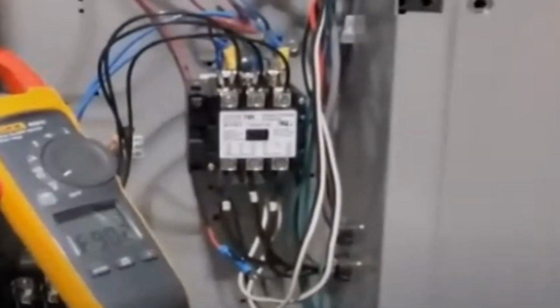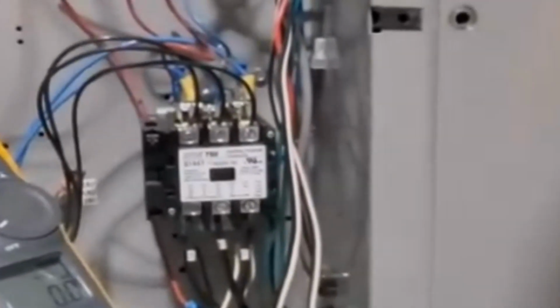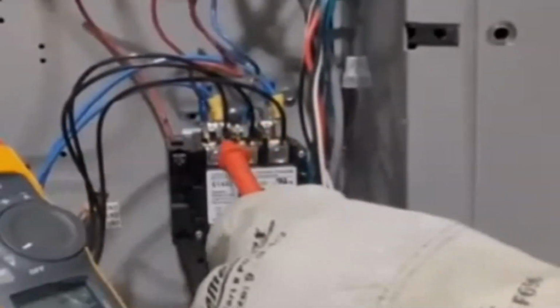We're going to wait for it to power up. All right, now this is a three-phase contactor. It's got 3 poles of power. It's got 1, 2, and 3. To check three-phase power, what we want to do is take our meter leads and go on the first and second leg, and we're reading 207. Then we want to jump across to the first and the third, 205.8, and then we want to go to the second and the third, 206.5. So that is how you check three-phase power.